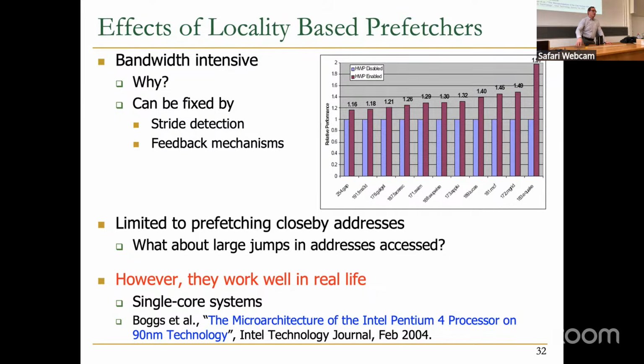So you're proposing basically designing a prefetcher for a particular core. I mean, it's certainly possible. You can have a private prefetcher for that core, right? But then we won't have any way to determine the stride, because the stride would depend on how we have distributed the data, how many things are processed by one core in your application, which is often determined by how we have written it. That's true, yes. Certainly, you partition your software, but there could still be a stride.